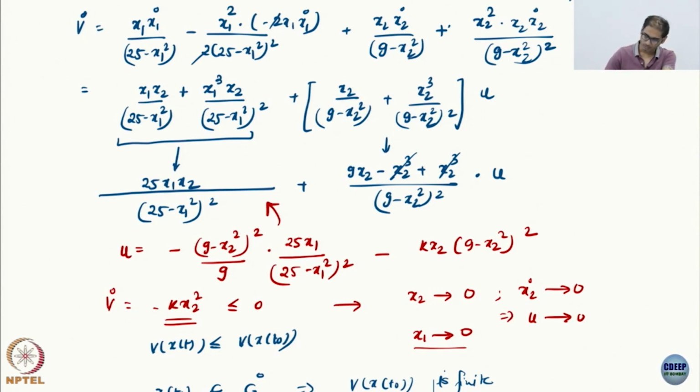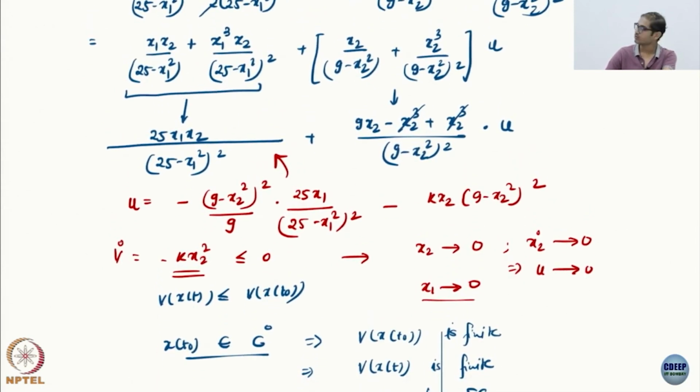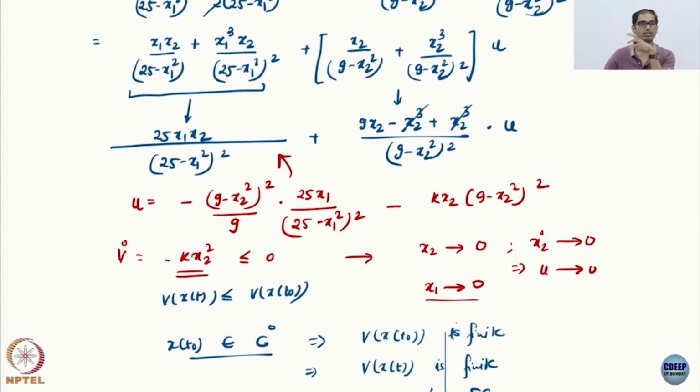But also notice that as you get to the boundary, the control here also does bad things. Control will also explode, at least on one boundary, if not on the other. Of course you are never going to go to the boundary, you already proved it, but the point is, if you started close to the boundary of the set, say at 4.99, the denominator in the first term of control is very small, so control is big. If you start closer and closer to the boundary, you are required to exert very large values of control. This may be somehow intuitive: I am already working at the corner of my operating region, so I have to work really hard to push it back inside.